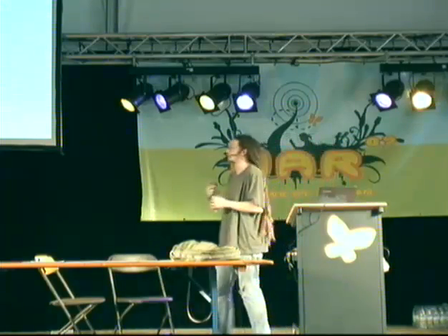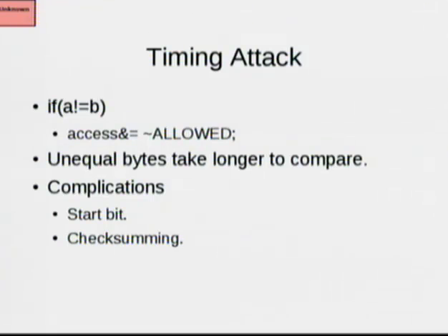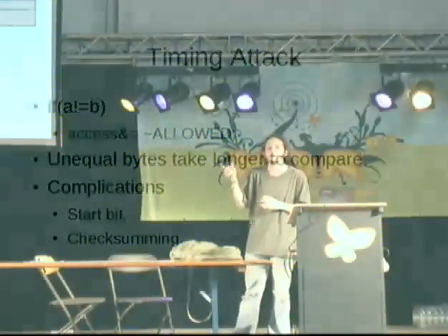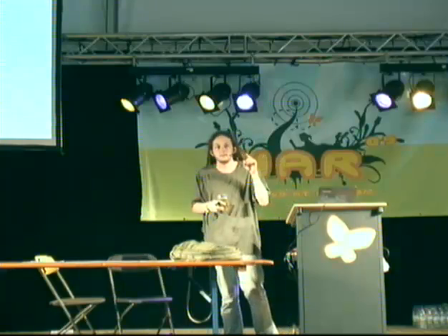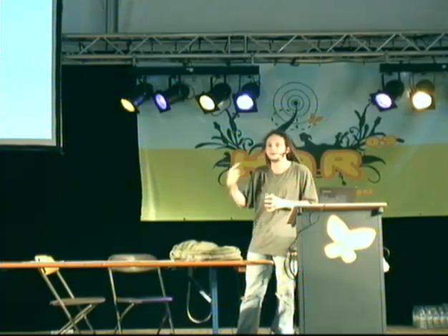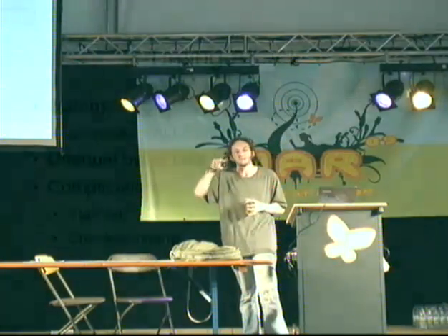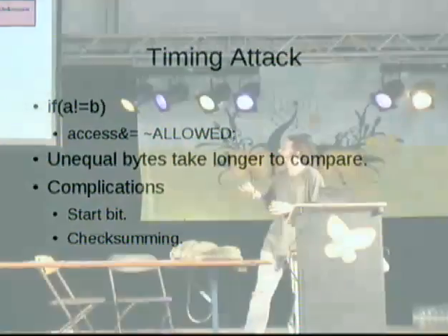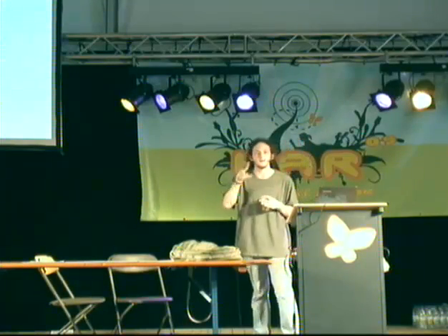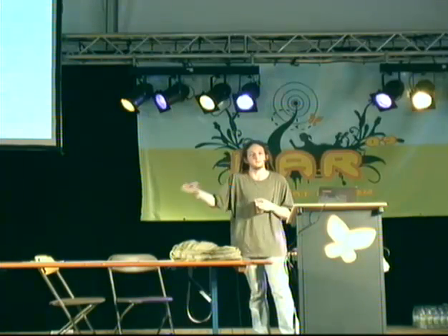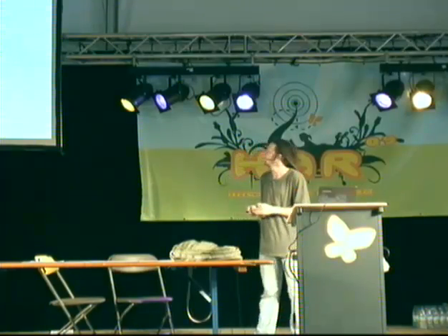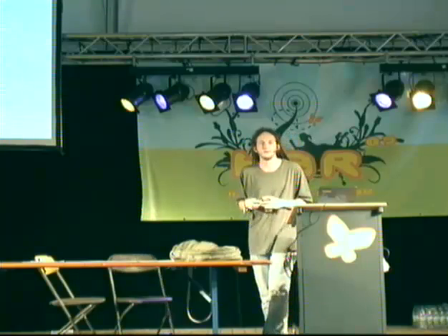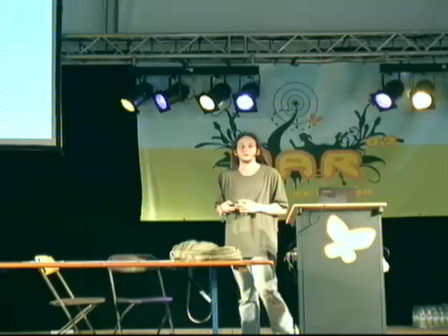And you have further complications. You have a start bit. In asynchronous serial, when you have an incoming byte, the line stays high and idle until that byte begins to be transferred. Then the line drops low for a single bit. That's called the start bit. And then the rest of the bits are sent least significant first. But if you look at the code inside the chip that's actually implementing this serial port, it will have a while loop that spins until the line drops low. If you know about this loop, then you know that to do a timing attack, you'll have to drop the line low early and then gamble on when the entrance of that loop would occur and begin shifting your bits out at that moment. I was lucky in attacking this in that you can slow down the serial traffic. You can make it speak as slowly as you please. You can even slow down the clock on some versions, which is handy.